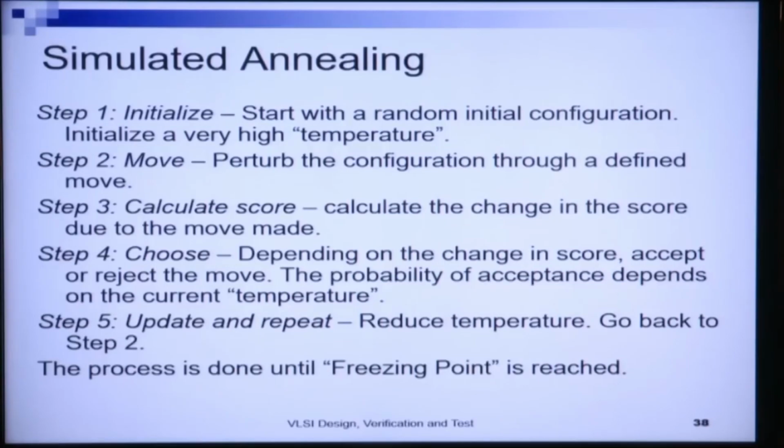Then we generated an initial solution and initial allocation of functional units and hardware registers to the operations and registers, and that gave me a cost of the initial solution in terms of the number of functional units required, the area cost of the number of functional units, the area cost of the registers, and the area cost of the associated muxes and demuxes.